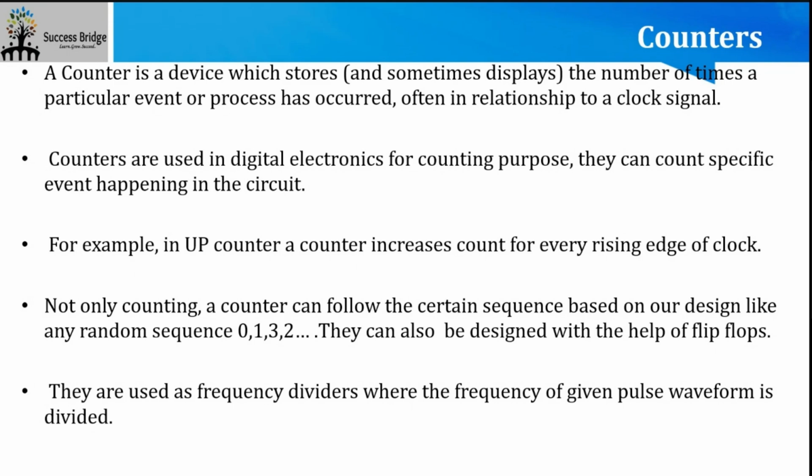So we have up counter and down counter. An up counter will increase 1, 2, 3 for every rising edge of the clock. Not only counting, a counter can follow a certain sequence based on our design. Like if we set up a sequence, it can also do that.